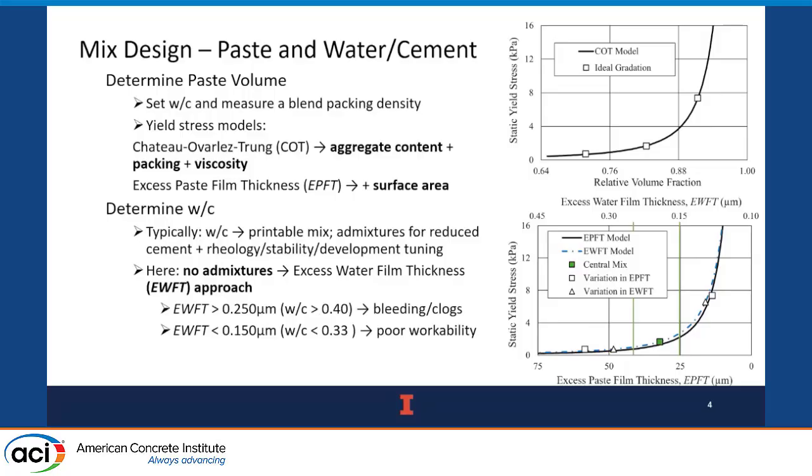And then if you drop below 0.33 water cement, you start to get into an unreasonable range, I would say, for the static yield stress of your concrete. You start to creep into the 3 kPa zone, which is just too stiff, I would say, for pumping and not necessary for 3D printed concrete. And so we kind of developed these windows here based off what's stable paste and what is a necessary static yield stress for our buildable sections.